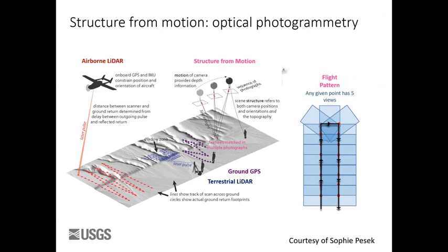So software does a lot of things. You guys probably know this. Up until a couple of years ago, the LiDAR was basically the gold standard for subaerial mapping. And it's always checked out with ground GPS, which is somebody walking around with a good GPS. Our GPS systems now, we're pretty confident that we can go back to hard points with approximately multi-millimeter accuracy. So any day we can go and measure a particular point within a few millimeters, given a good RTK system. And LiDARs, of course, can give you that kind of thing.